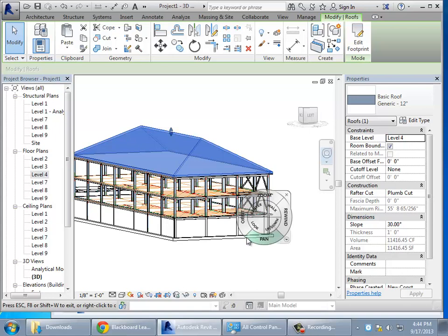What you got to do is actually go through and create something called a reference plane, which is matching the slope of that. Because we can put beam systems on floor planes, we put them on wall planes, or we put them on a reference plane that's kind of matching some other angle, which is interesting. The slope of this roof is actually a reference plane, which is really, really interesting. So here's how that would look.